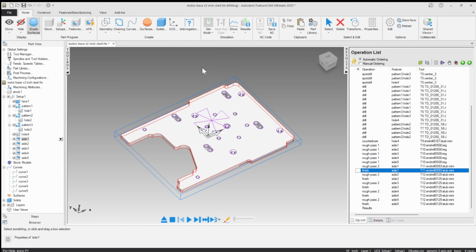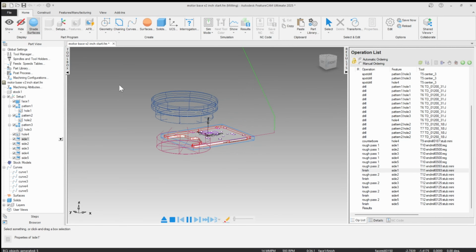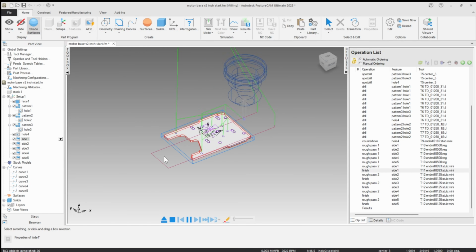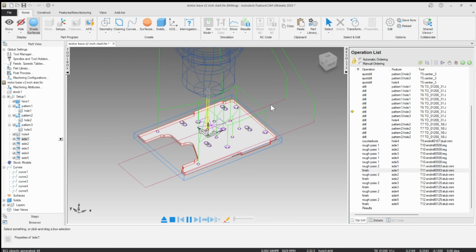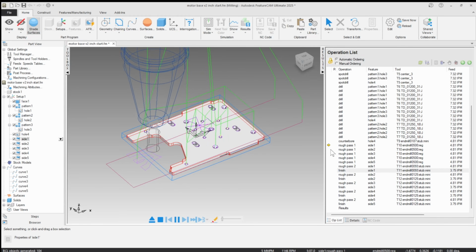So I'm going to run what's called a center line. I'll just run this slow for the first time. We'll see the tool, and the color green means rapid. The other colors you're seeing are the feed rate moves, so the moves at whatever specified feed rate. I want to draw your attention to the right-hand side while this is running as well. This yellow arrow is moving down through the list and showing us exactly where we are.